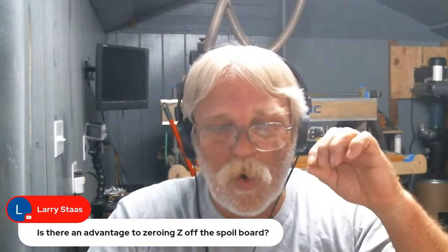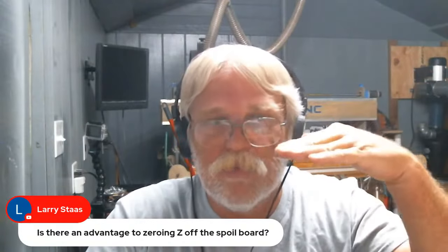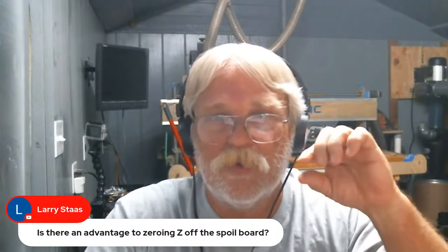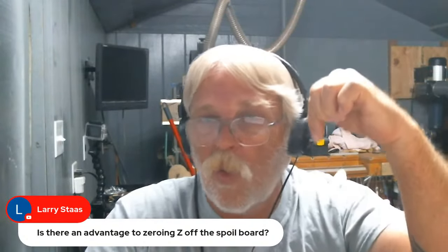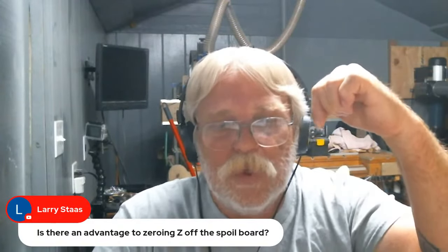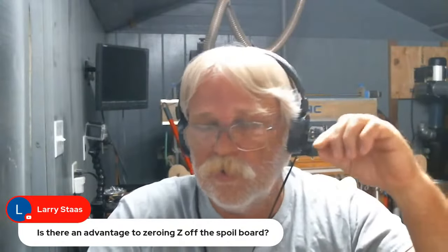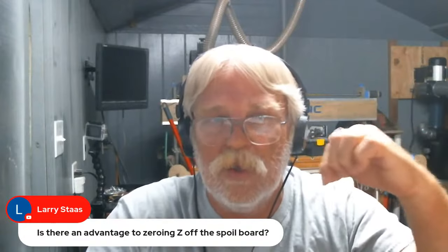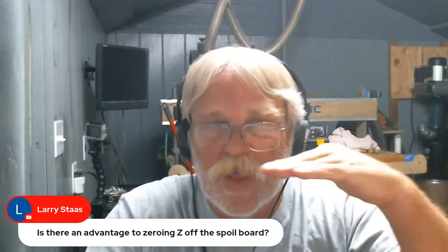If you are cutting a pocket and the depth of the pocket from the surface of the material is the critical measurement, like if that pocket needs to be 1/4 of an inch deep, let's say, if that's the case, setting your Z0 off of the surface of the material is the important thing, because it'll go a known distance from that surface.